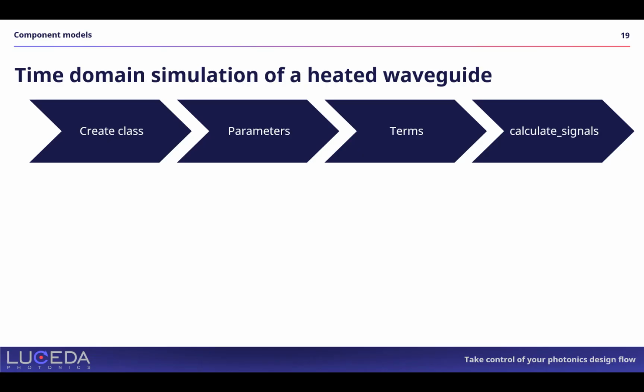So let's look at a more advanced example. Our circuit simulator Caphe is equipped to conduct time domain simulations as well. Earlier we looked at frequency domain simulations, which are useful for analyzing the steady-state behavior of photonic integrated circuits, particularly for linear and time-invariant components such as filters, couplers, and resonators.